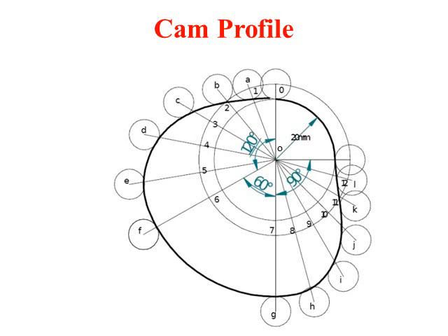Now, once after drawing the pitch curve, with A as the center and the radius equal to that of the roller, draw the circles at different points A, B, C, D. We need to draw circles, and the circle radius will be equal to that of the roller. Once all the circles have been drawn, join the bottom of all the circles by a smooth curve. So this curve is what we call the CAM profile. So this completes the CAM profile when it is inline.